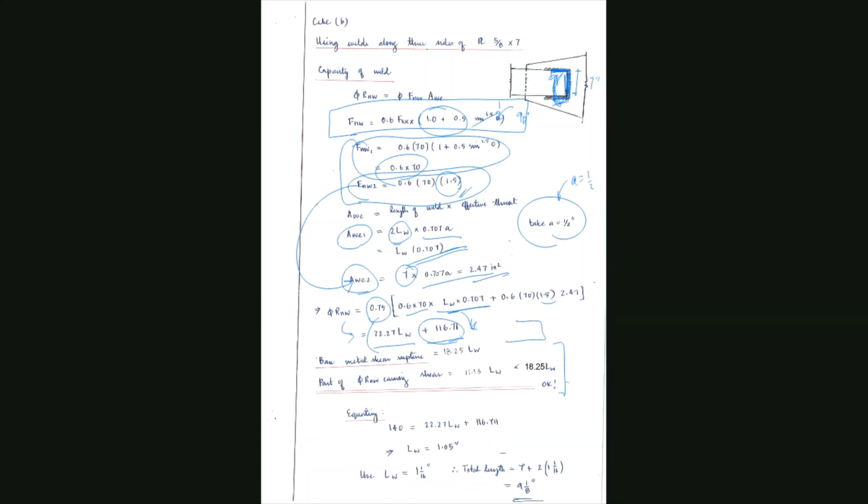This part of the weld and this metal causes a tension here. It is not shear. Okay. And it is safe in tension because the T_u which is given to you has already considered the yielding and rupture. So it is the safe value that is given to you. So you don't have to check for tension.